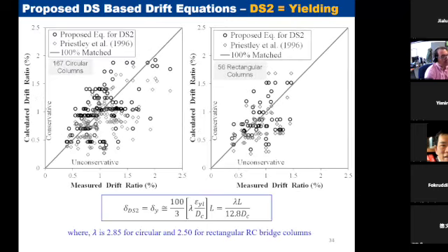And we repeated that for 4 and 3. At 2, which is the point that shear cracking starts, we noticed that that's very close to the yield point, and we don't have that many pictures in our database to relate that. So we borrowed the equation by Priestley, adjusted with the new database, and made a one-line equation for rectangular and circular columns to find damage state 2.